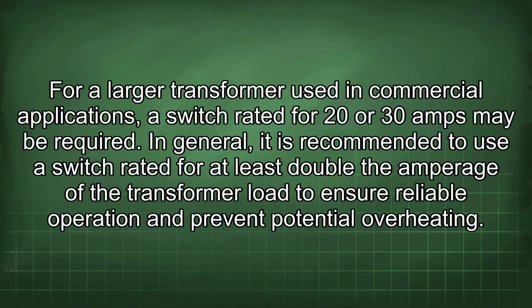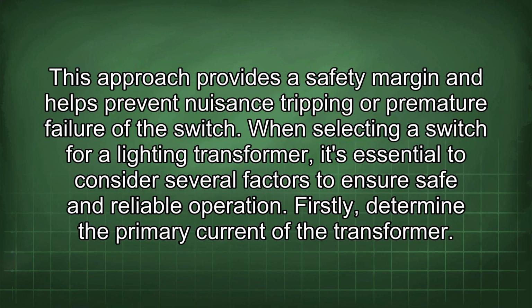In general, it is recommended to use a switch rated for at least double the amperage of the transformer load to ensure reliable operation and prevent potential overheating. This approach provides a safety margin and helps prevent nuisance tripping or premature failure of the switch. When selecting a switch for a lighting transformer, it's essential to consider several factors to ensure safe and reliable operation.